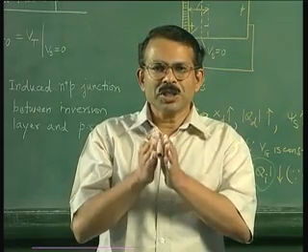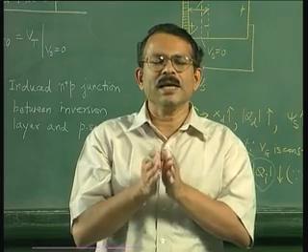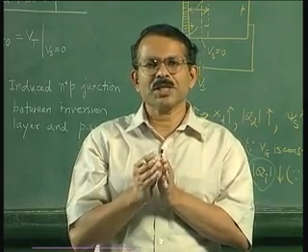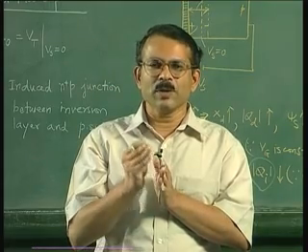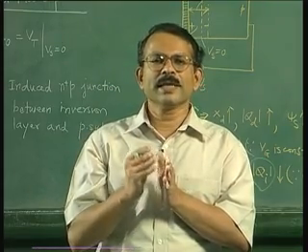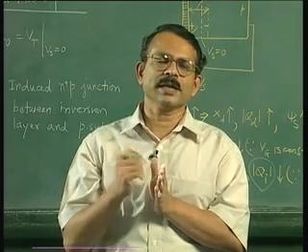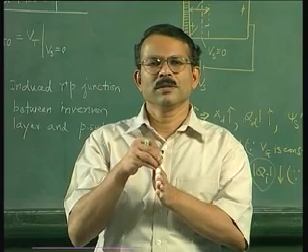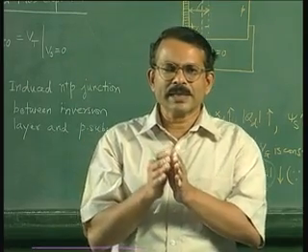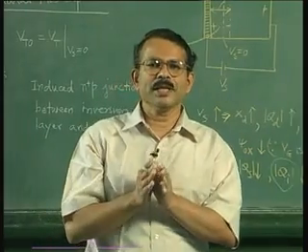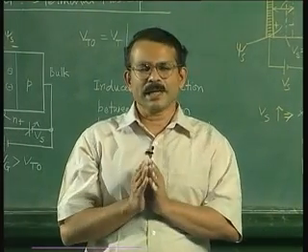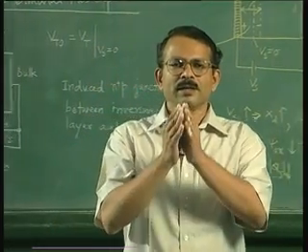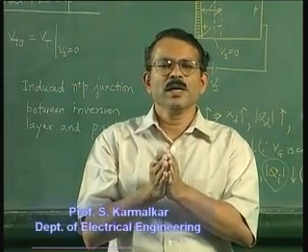Okay. Now if inversion charge becomes 0, obviously the device has reached a threshold condition, okay, because threshold condition corresponds to inversion charge just starting to increase if you are increasing the gate voltage. On the other hand, if you are decreasing the gate voltage, it is a point when the inversion charge just goes to 0. Now in this case we are not changing the gate voltage, but we are changing the source voltage, but that does not matter, right. What it means is, as you change the Vs, at some point the inversion charge is coming to 0, and therefore this is a threshold point.